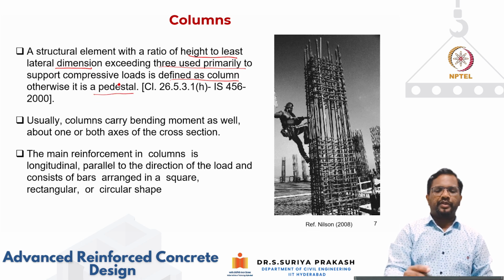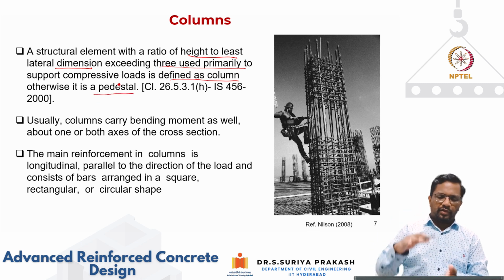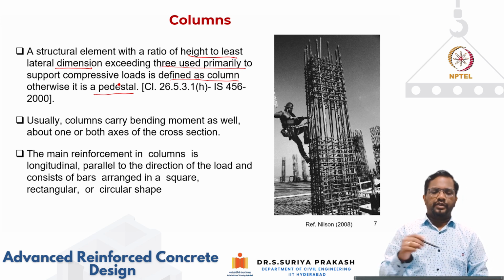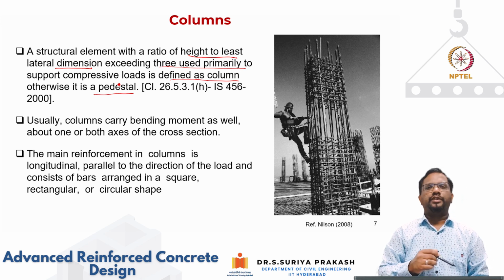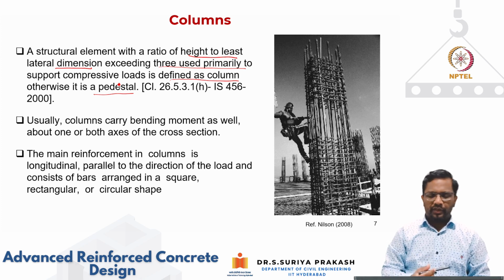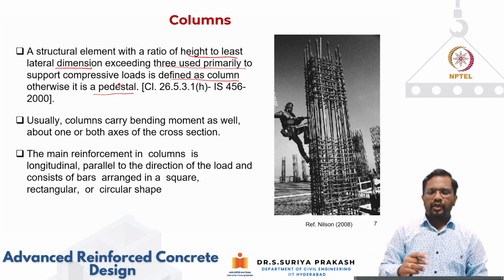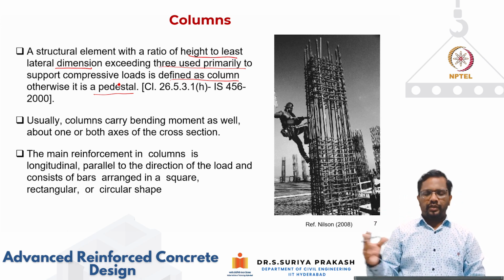Otherwise, it's called a pedestal. It's a stub column, or a very short column, with the height to the least lateral dimension of 3. Then we call them a pedestal as per the IS 456 provision. The pedestals are predominantly compression loads, but columns can have compression and bending.